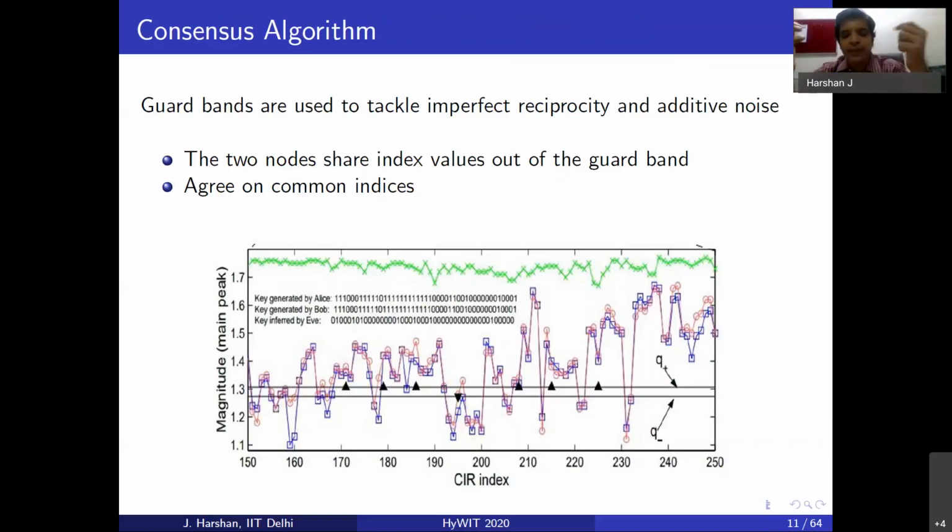Now, with the use of guard bands, what they do is divide this entire zone into two levels, which is the simplest case of generating a bit out of a sample, and then they don't mark a single boundary. This boundary is also relatively thick. The reason is that if they make it thick, when we have a sample that lies inside the guard band, they're going to discard it, because potentially the sample in the guard band might have come from the adjacent region. And this could eventually lead to an error between the bit strings that both of them possess, right?